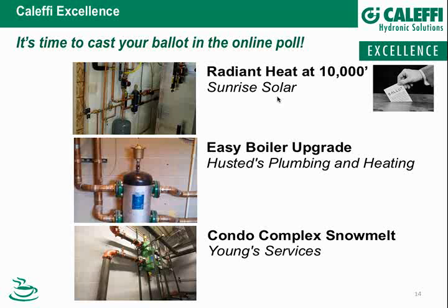Some of the geothermal pumping stations that you see in the market today, if you take them apart and look at them, one company in particular will go anywhere from one circulator all the way up to 4 circulators in series. And the way they do the 4 circulators in series is they have 2 sets of 2 closely coupled pumps, basically in a push-pull arrangement.